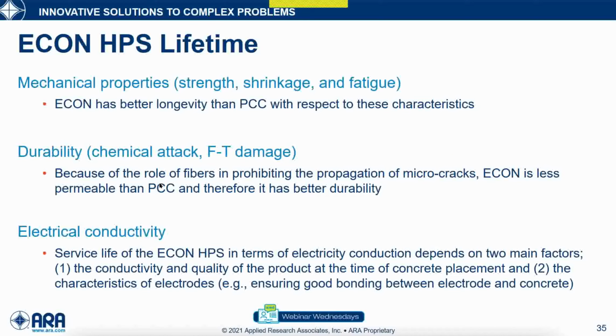And in terms of durability, since we are eliminating de-icing chemical agents, this is good for bridges too. When you eliminate the application of de-icing chemical agents on bridges, it will not only save you from incidents and accidents from ice and snow accumulation, but will also improve the durability and extend the surface life of the bridges, because it will eliminate the corrosion.